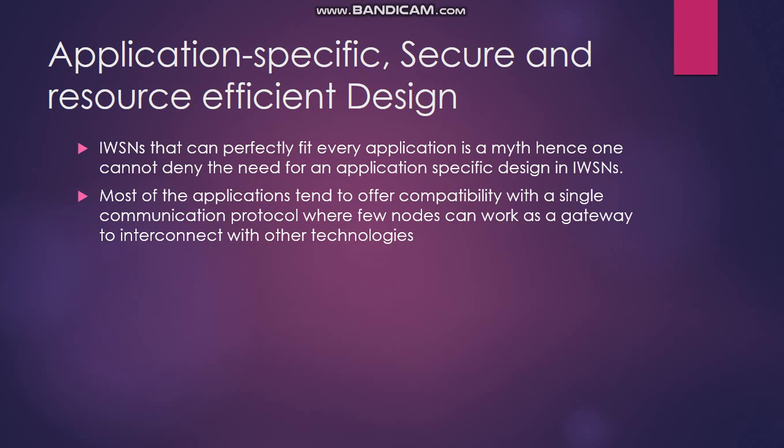Apart from this, if wireless nodes are used to develop a generalized solution which can work in a wide variety of applications, it might need a lot of resources. For instance, Zigbee, WirelessHART, and all those. With the maintenance, modification, deployment, packaging services, and unit costs, the solution becomes unfeasible. Therefore, most applications tend to offer compatibility with a single communication protocol, where a few nodes can also work as a gateway to interconnect with other technology.